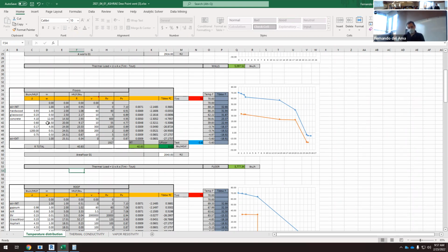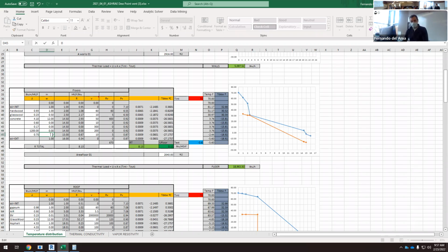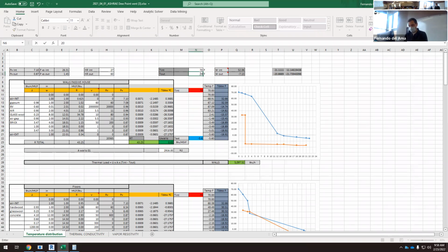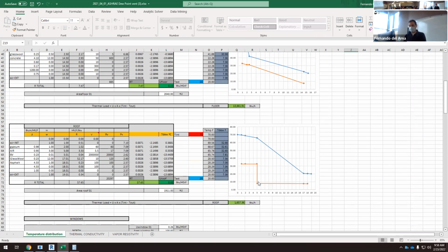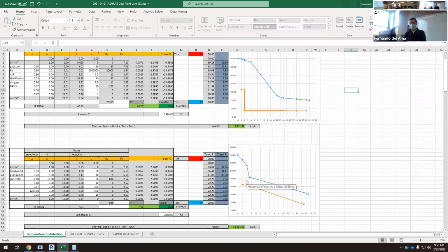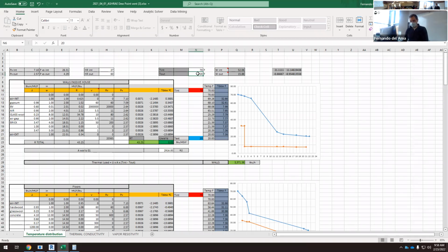With these conditions, this is 0. If you have more layers, make sure that the width is always 0 and it won't affect. So we might have a condensation that we are taking into account, that the outdoor temperature of this floor is negative 5.6, and usually it doesn't happen. Okay, so if the temperature were just 20 Fahrenheit, we wouldn't have condensation issues in the floor. Okay, so we can leave this that way.